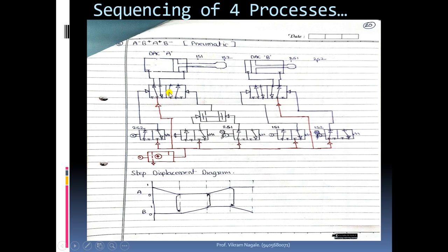Okay, right side block logic इकडे आहे ते मी इथेच explain करेन. Now whenever we want to show retraction, we have discussed many times that whenever we want retraction we have to pressurize this 5x2 valve from the right side. Okay, then and then only the connections will get shifted to the right side block and the air will pass as per the internal structure of the block.